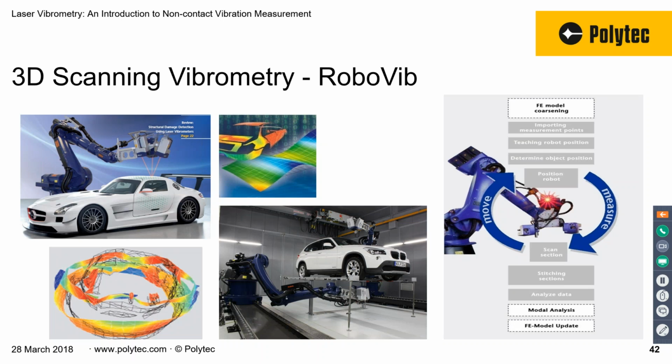So we can very easily take all that position data, combine it with the vibration data, and get a full three-dimensional map of the entire visible surface of the vehicle. And those data can be integrated with measurements from hidden points that could not be reached with a vibrometer, say from accelerometers that are mounted inside the vehicle somewhere where you can't get laser access to those surfaces.